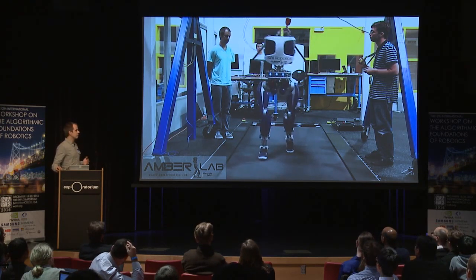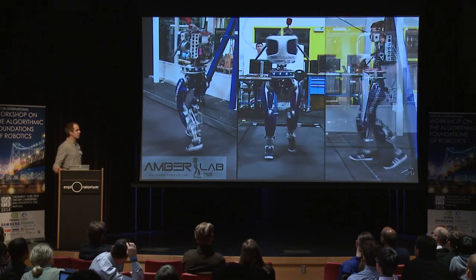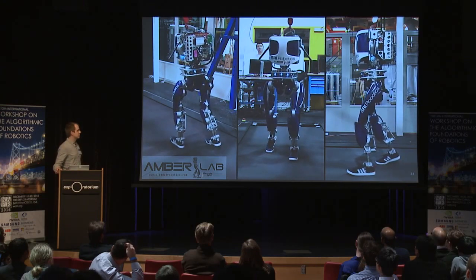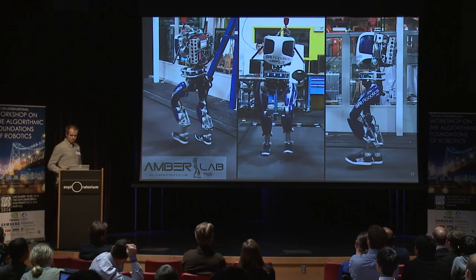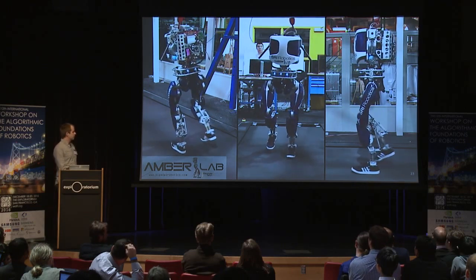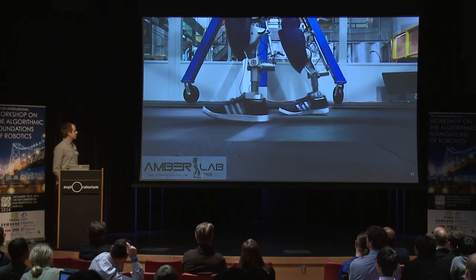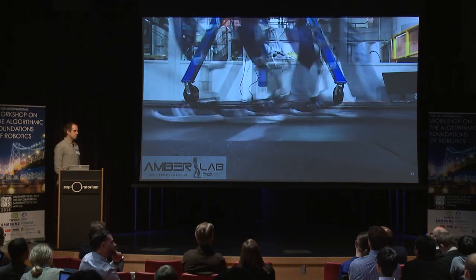And I definitely agree, a lot of the energy efficiency that we're getting with this robot is coming from all of the gearboxes and the transmissions, and the fact that we're using very efficient motors. But another thing that we're leveraging is the passive springs in the ankles that are able to compress and absorb some of our impacts as well.